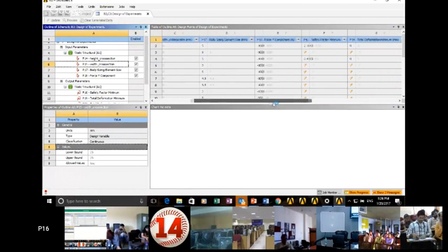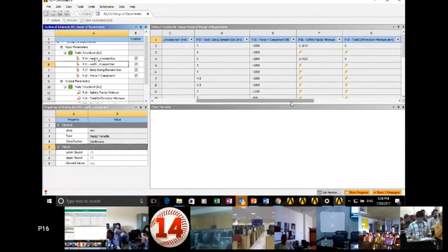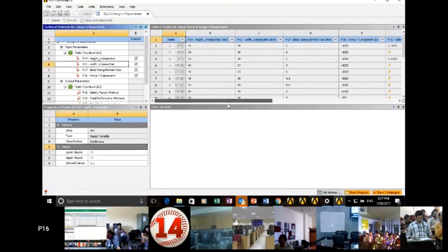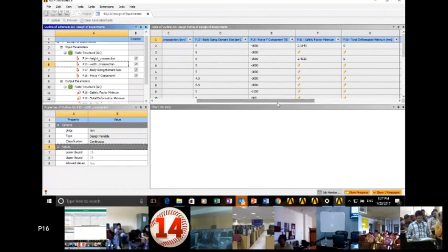Right now it is updating. So what it will do is automatically trace the value of factor of safety for all those ranges of values. Once we obtain the factor of safety at different value ranges, we will simply plot a response surface for that.